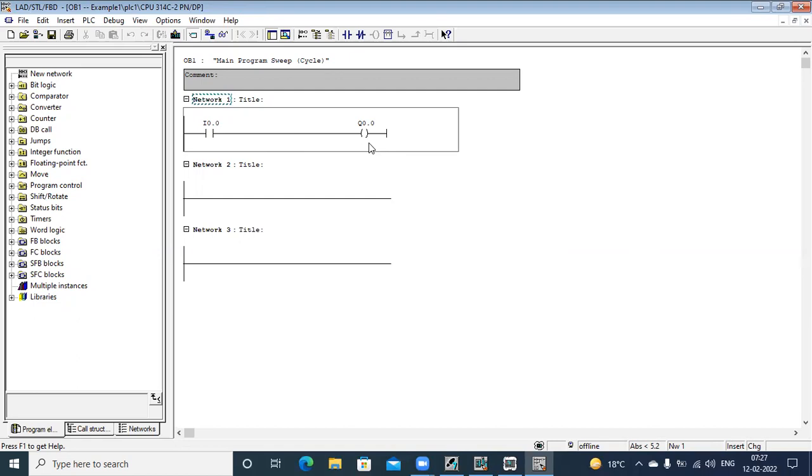In case you are using a push button, it's a momentary switch. It means when you press, it becomes on. When you release the button, it goes off. It comes back to the original position, so that becomes zero. But when I press the push button and release, your output should remain on. It should hold. For that, we need to use latching here.